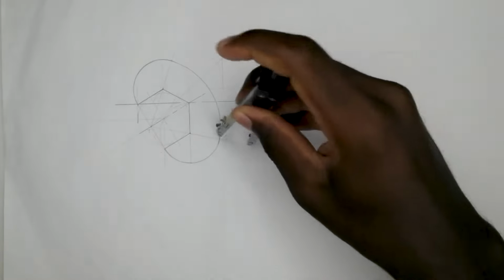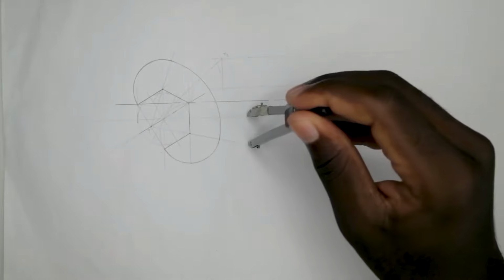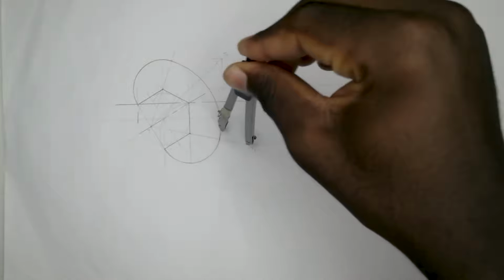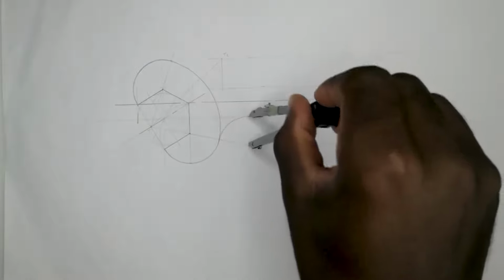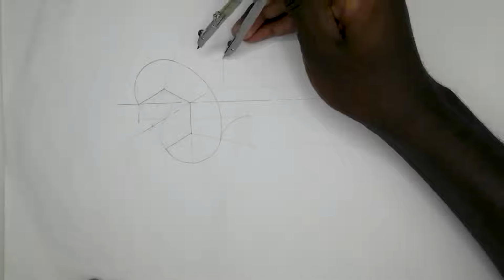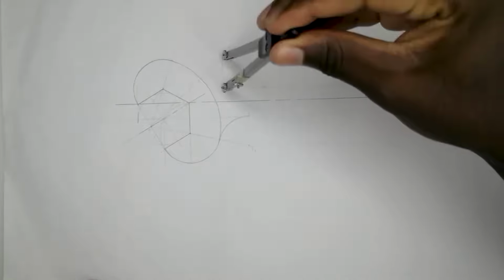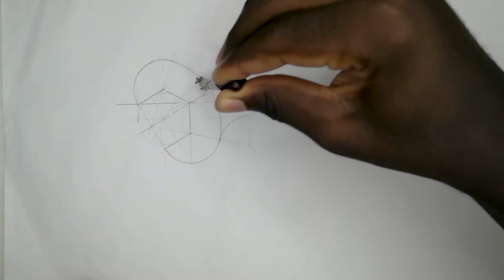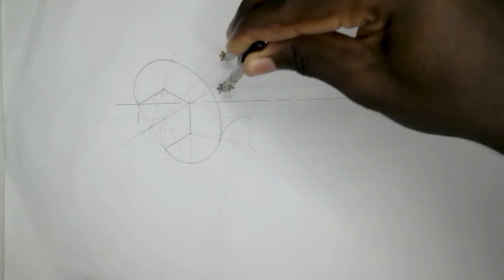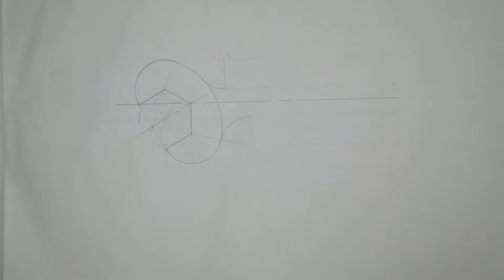So this is where our arc is going to touch the other arc tangent. So we'll get a compass, stand at point T1, open to the point of tangency, which would be the same as the other one there. Then draw an arc. You can see I have my arc tangent, which looks nice. Then stand at T2. You can see I haven't changed my radius and I still have the same points of tangents. This is what should be happening even when you draw. Everything should just fall into place. So we have our handle drawn.